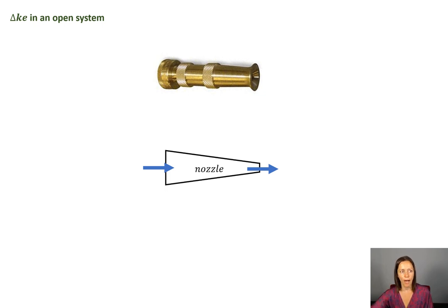And so I would do a control volume analysis. I would draw a control volume around a region of space that I'm interested in analyzing. And so I would be looking at changes from that first arrow to the second arrow. So the kinetic energy of the fluid crossing the boundary at that first arrow on the left would be 1/2 times v1 squared.